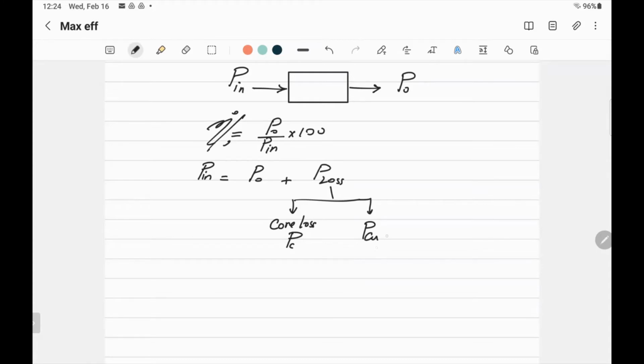So it's equal to I squared times R. Working with the transformer without the equivalent circuit, you have primary side, you have secondary side, so you've got to get the copper loss in each side. Like the primary side, say I1 squared times R1.